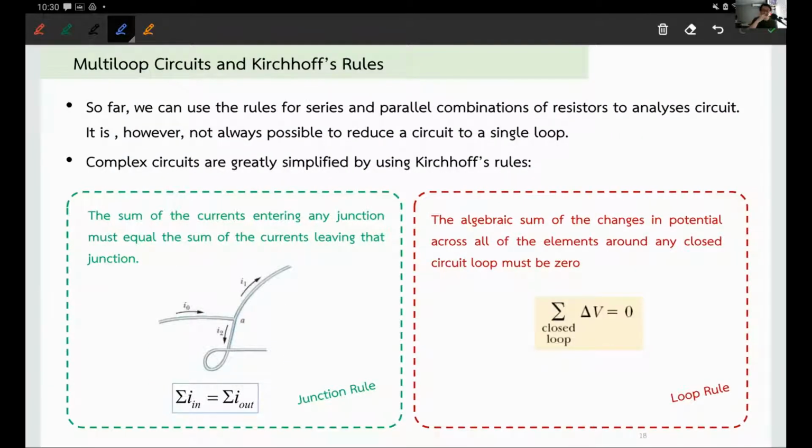All right. So we are going to look at Kirchhoff's rules now. This is something I mentioned about the recipe, in the sense that once you understand how to apply Ohm's law and understand what's happening at the junction, because you saw what parallel connections do with the current flow, and whenever you have a series connection, the current just keeps going. That allows you to understand these two rules by Kirchhoff, and eventually this allows you to do multi-loop circuit analysis.